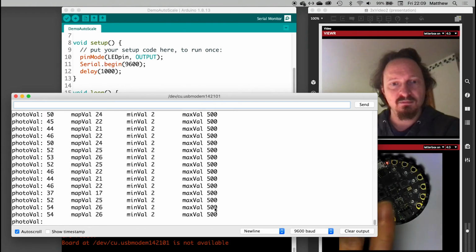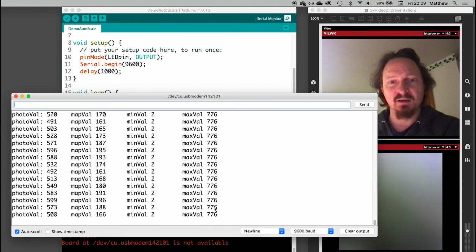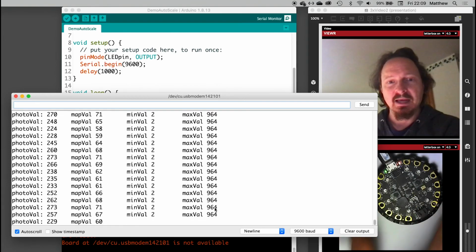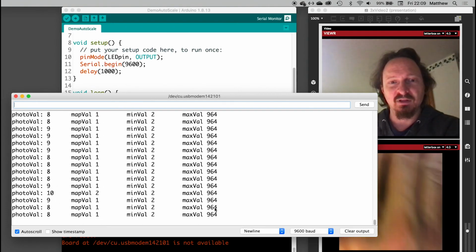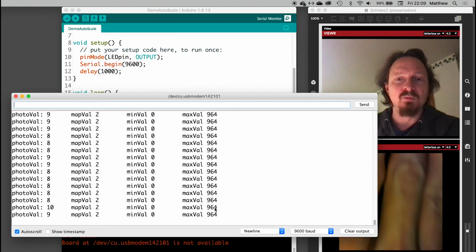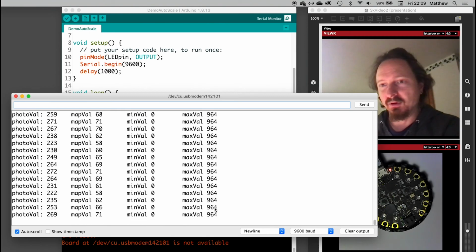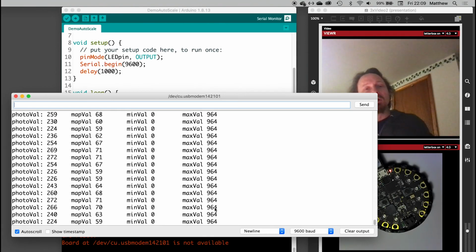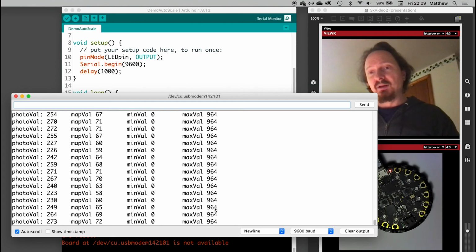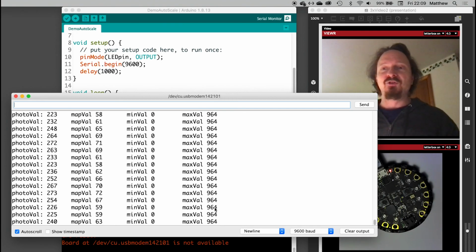2. And if I move this close to that lamp again, we can get up to 964. And so now our range for this sensor, as I move my hand above it, is going to be more accurate to the environment that we're in. So when you're working with analog ranges and installations in interesting or dynamic environments, this can be a helpful tool to automatically adjust your ranges.